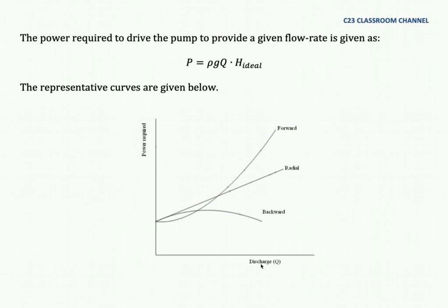But if you see the relationship between discharge and head here, you will find that if you increase discharge, sometimes the manometric head, or the head of the pump, will not increase. So it means there is no need to increase the discharge, because it only increases the power required.